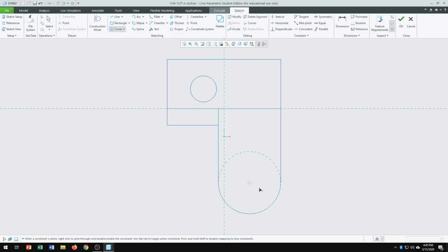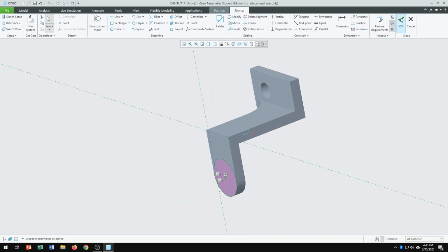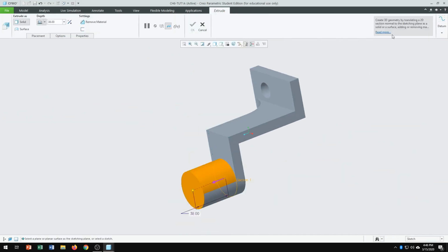I'm going to click on a circle, so this will be a concentric circle. You will see it says equal. It should say equal. And then when it says equal, just turn the shade back on. It's right there, and then you click OK, and then you go to options. Just make sure you click on options. It gives you the two-sided cylinder. The cylinder two-sided, and make sure it's blind.